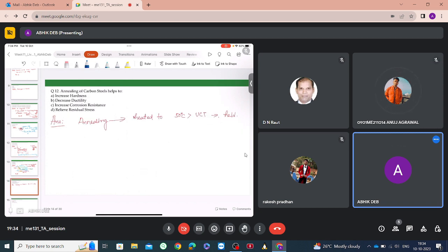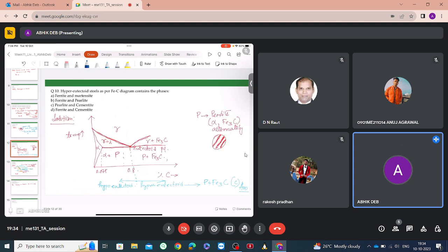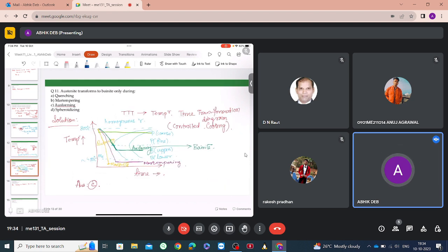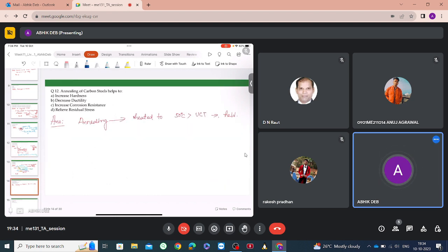Okay sir. So it is heated to 50 degrees above the upper critical temperature, somewhere here, and it is held, so as to decrease the hardness and increase ductility.